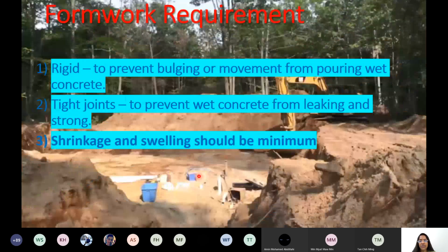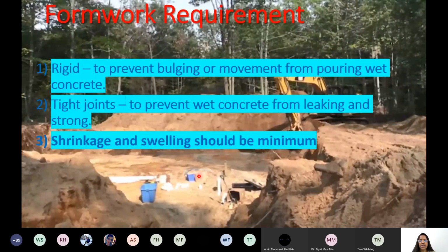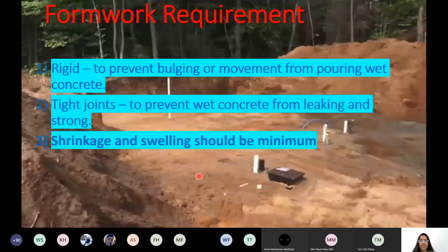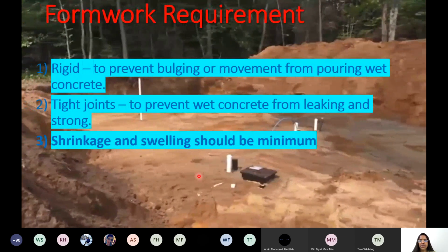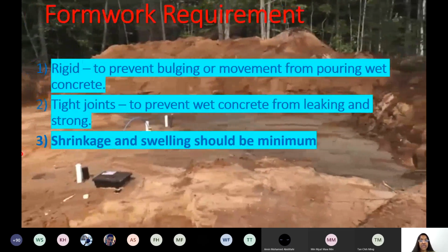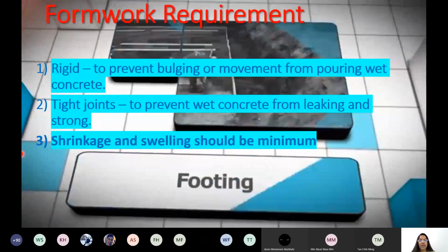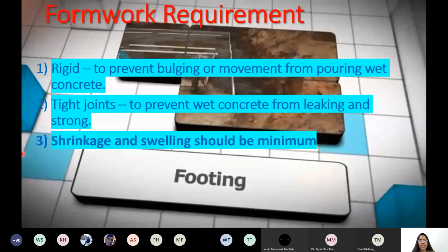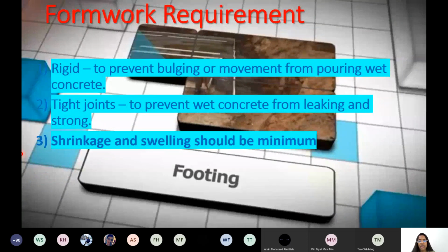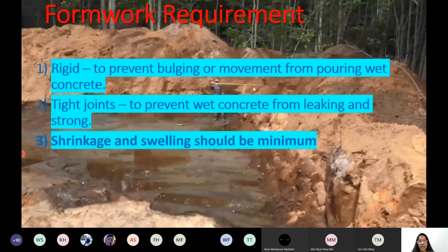Okay, when can you say a formwork is a good formwork, the best formwork, reliable, cost effective, right? There are so many factors involved, and as an engineer you have to know the requirements. Let's see one by one. Rigid. Your formwork should be rigid, strong enough to take over the load coming in, right? There are three types of loads mainly: the concrete load, which it is going to hold, staying there until it's set, right? There are a number of days given there, right?